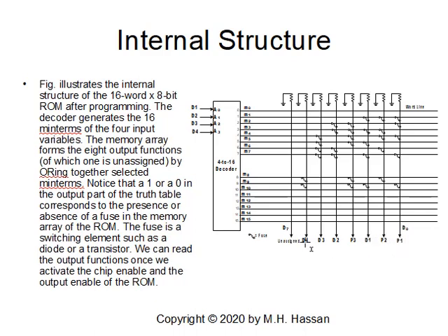So for instance, D4, we are choosing only M4 and M5. So those switches will stay intact. They will stay closed. It means there's connection with the minterm. And all the other switches will be blown. It means there is no connection. The same thing, for instance, for D3. D3 will be M4, M5, M6, and M7. You see those fuses are intact here. Okay? And so on and so forth. So this will be the connection for the EEPROM after you program it, after you burn it.